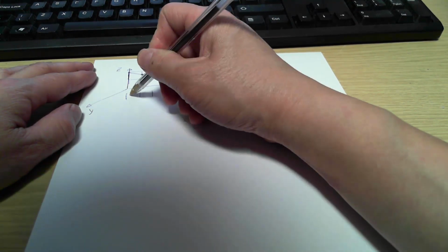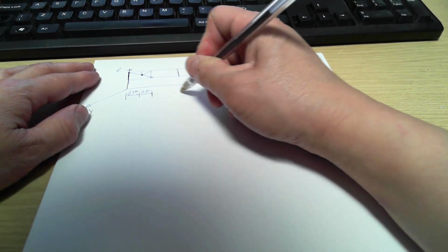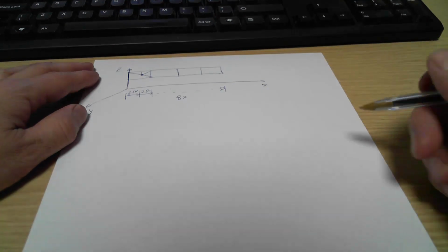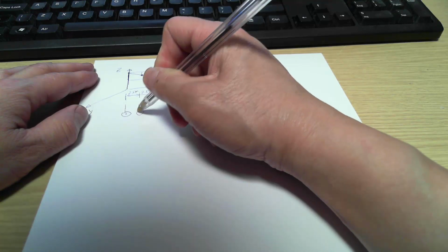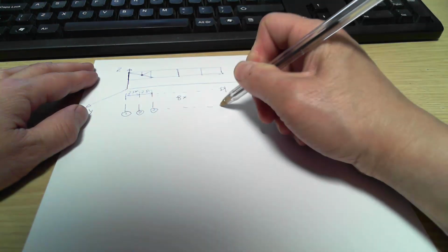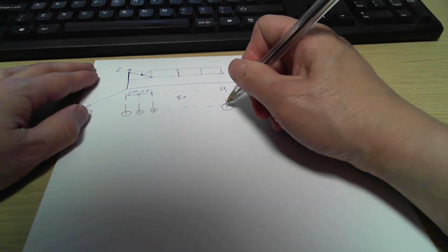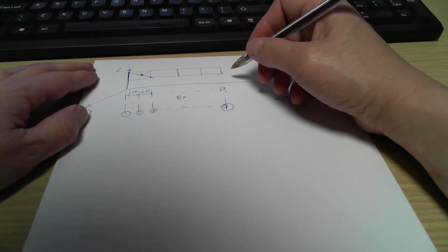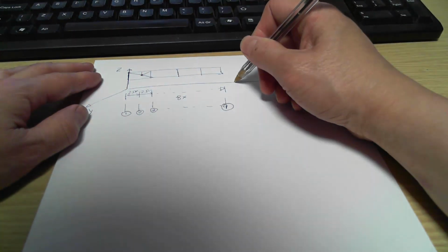So because of this, you have 2.5 meters for each bay here. In total you have 8 of them, so I won't draw them out one by one. If this is grid line 1, and then line 2, and then line 3, and so on and so forth, the last one is going to be line 9, because you get 8 bays in total, so 9 lines. In that direction, you have the first line, which is the ground floor, which comes here.